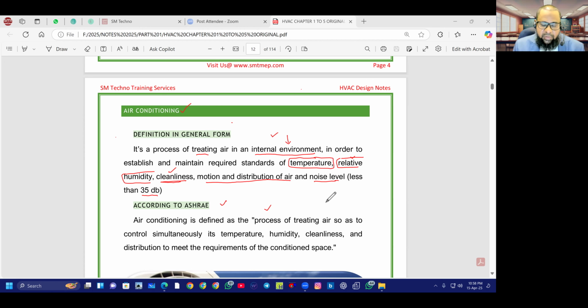But we consider ventilation separately, because you'll find a separate exhaust system that also comes under ventilation. That's the reason we are not keeping it in air conditioning. In the kitchen we require separate ventilation, and its purpose is different: not for maintaining oxygen level, but to exhaust the fumes and heat from cooking. Similarly, in the toilet area, ventilation is required; that also comes under the exhaust system, to exhaust the foul smell.